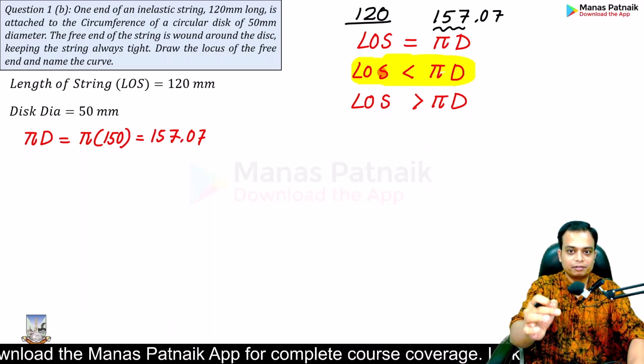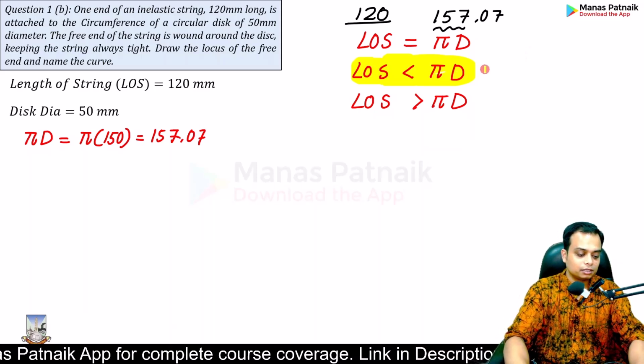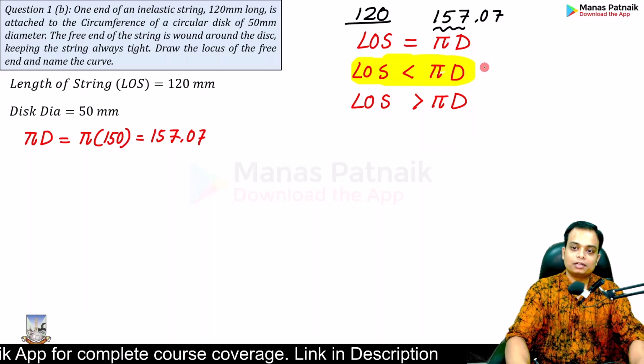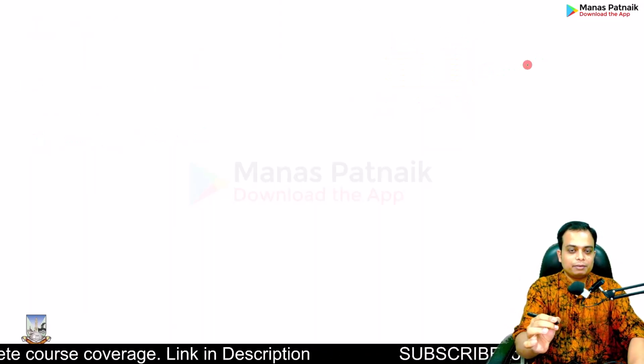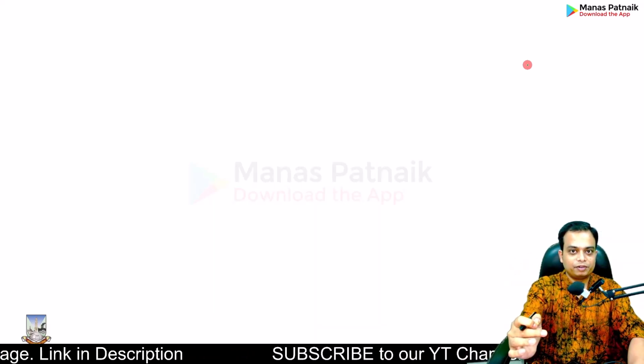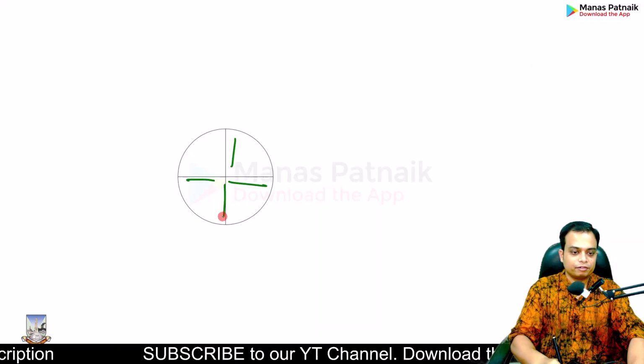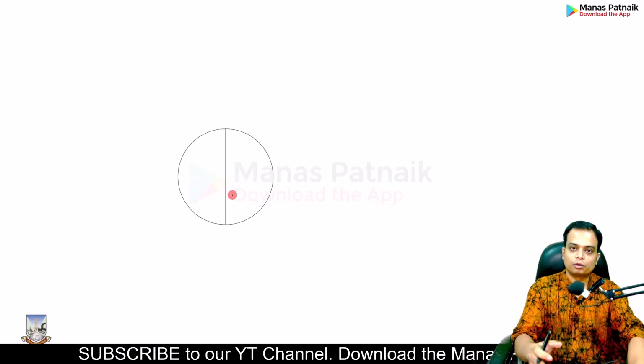This is going to be fun. Here we go. If you want to take a screenshot right now, take it. This is going to be helpful. This is what we need to implement. Start by making a circular disc, a circle. Diameter is 50, so the radius is 25. That's 25, 25, 25, 25. Done. Very easy.